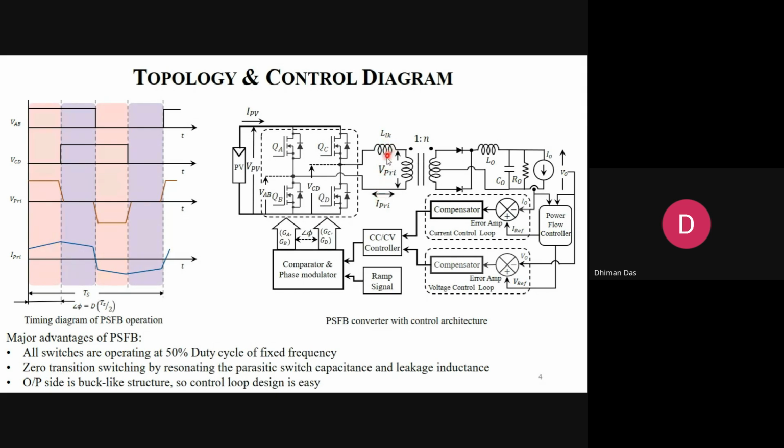Now, when you control the slope of the current for this small duration, automatically your power transfer capability from primary to secondary will also reduce because you are restricting the current flow. So this inductor also acts, when the output is short circuited, to limit the current inherently.